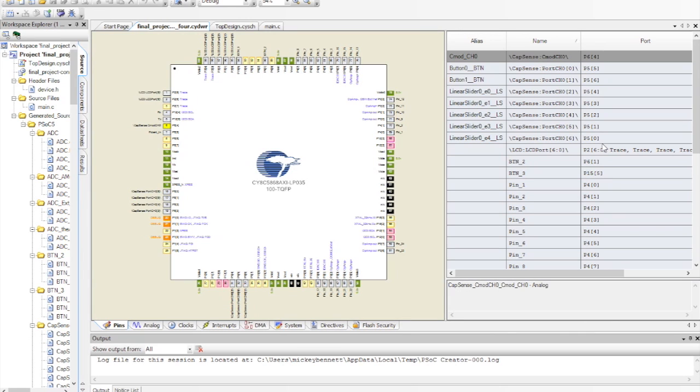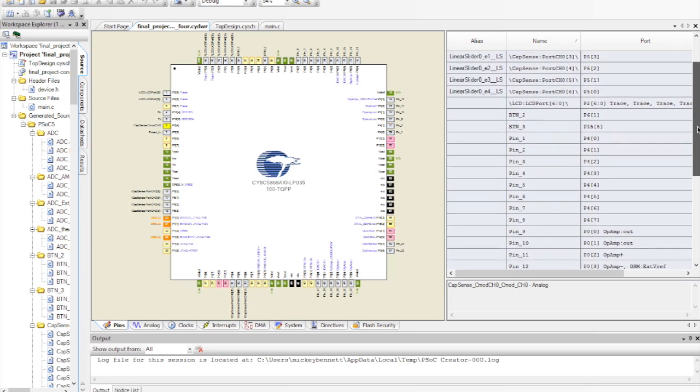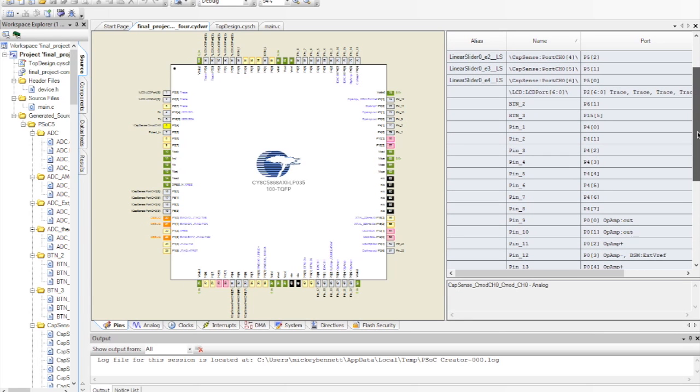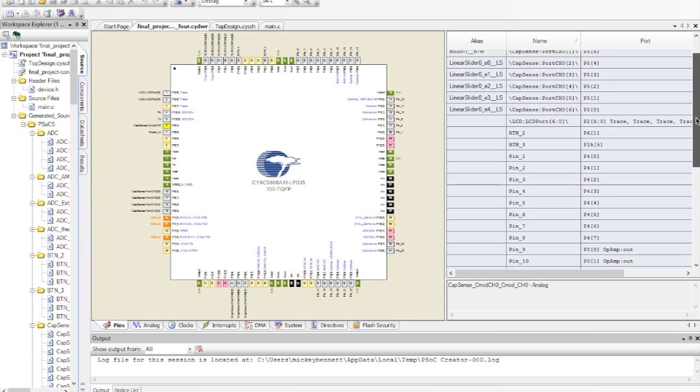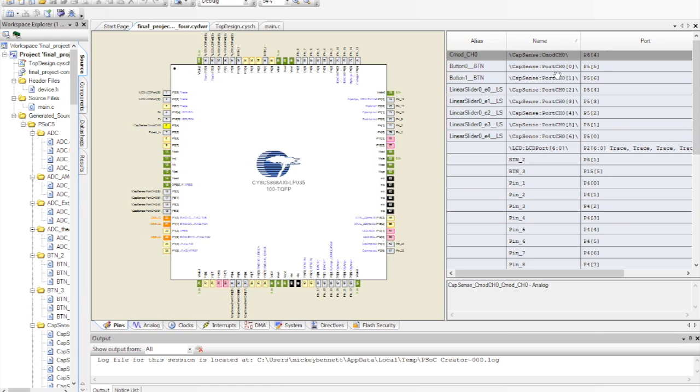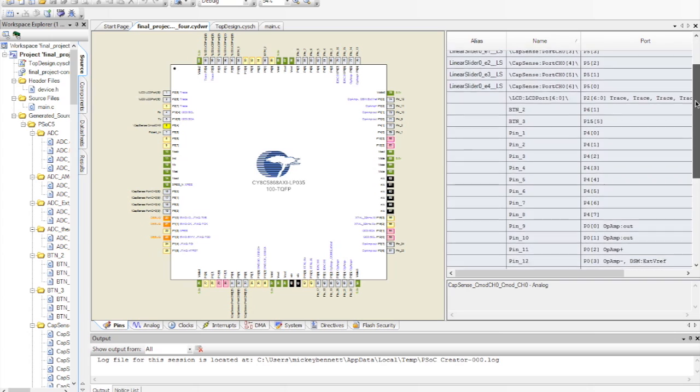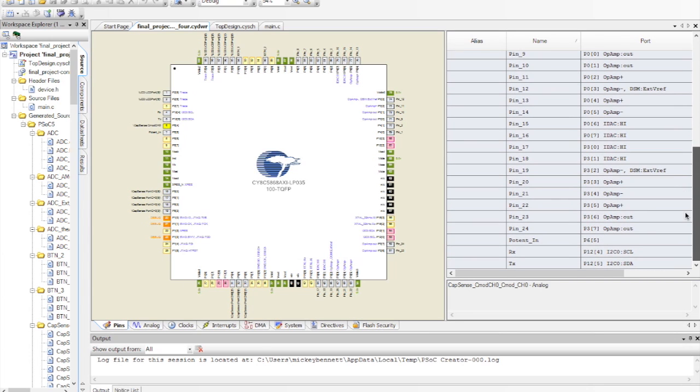Pin layout, there was a lot of them because I did the direct connect way. It was a little challenging with all the pins, but it saved me having to wire the shift registers, which I found to be nice. Nothing special about the pin layout other than they were just all on the same side except for the CapSense. The CapSense needed to be these particular pins because that's how it's laid out on the board and it's described in the datasheet. Potentiometer is fixed because it's a fixed pin, and RX and TX were just chosen for convenience.